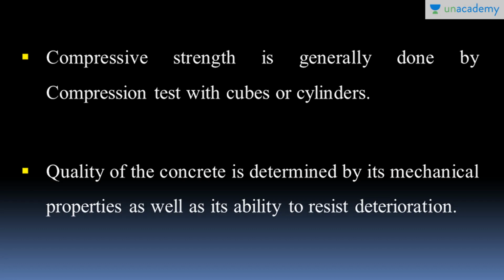In the previous slide we understood that strength is measured in different forms. So how is it measured? Compressive strength is generally determined by compression tests with cubes or cylinders. This will be very familiar to final year students and other research scholars. Almost all compressive strength testing is done on cubes and cylinders, either in a compression testing machine or using a UTM.